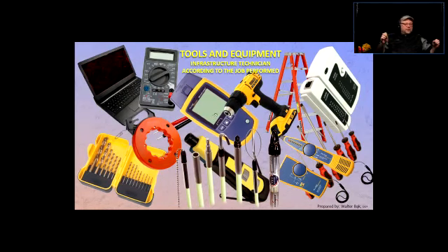Kinks in the wire. So if you run the wire and it just does a little bit of a kink here, right? And if it does that, there's a kink there. That also disqualifies the cable from Cat 6 at least. Okay, so it is extremely important to take care of those wires.